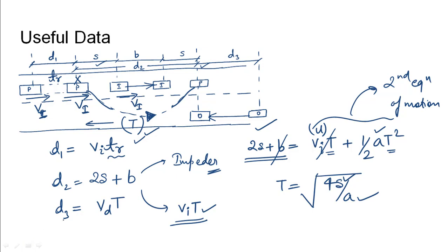On adding these three components together, we would get OSD, that is given as d1 plus d2 plus d3, that is the overtaking sight distance on a two-lane two-way highway that must be provided so that a faster moving vehicle can pass a slower moving vehicle safely against the traffic in the opposite lane.